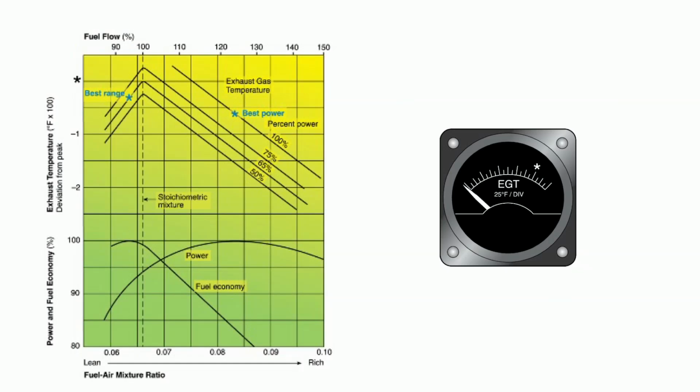Now, reciprocating engines in aviation are a little bit funny. When they aren't directly injected, and due to a couple other factors, the way that the intakes are built and things like that, our stoichiometric value actually isn't the best ratio of fuel air to operate. In most cases, a ratio of around, say, 12 to 1 is more efficient for those engines. Part of it has to do with the fact that we're going to lose some of the fuel that enters the airstream before it gets out to the cylinder. So running a little bit rich is actually going to help us produce more power because by the time the fuel and air get to the cylinders, it's going to be closer to a best power range of fuel to air mix.